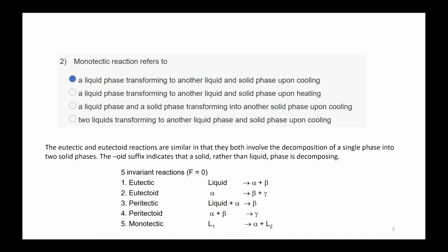Ma'am, does that mean supercooled is like glass forming, similar to that amorphous form, isn't it? So does that mean the martensite has no particular order? No, martensite is metallic. It won't be like glass; it will be a metallic structure, but it will have a very high density of defects.